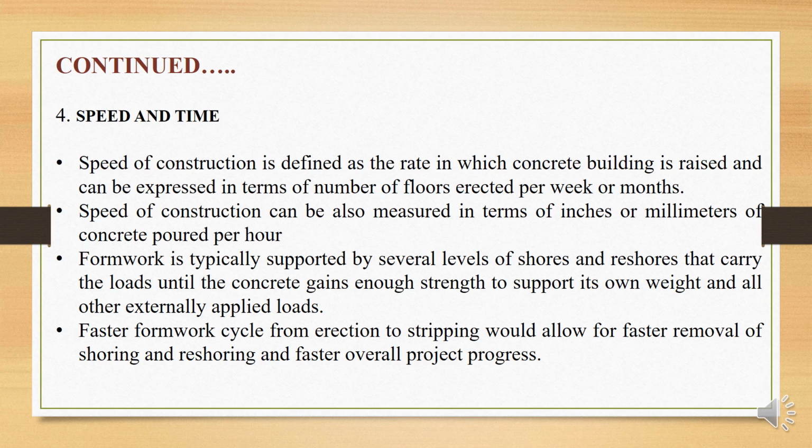Formwork is typically supported by several levels of shores and reshores that carry the loads until the concrete gains enough strength to support its own weight and all other externally applied loads. Basically, shores are vertical members made of wood that support recently built concrete that has not developed full design strength. On the other hand, reshoring occurs when the original shoring is removed and replaced in such a manner as to avoid deflection of the cured concrete.